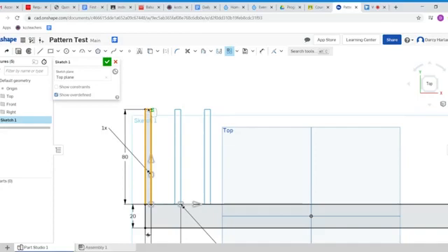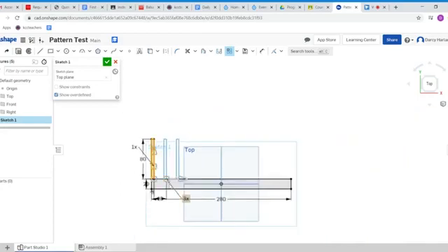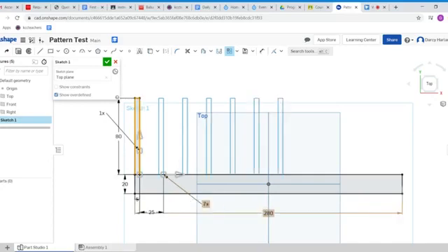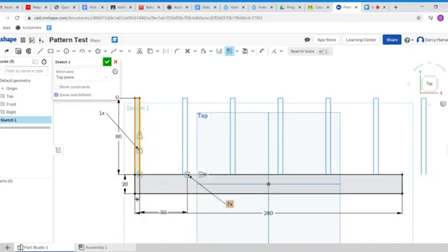So just select those 3 lines there, and you'll notice there's some other information that comes up when you have selected this. First of all, it's giving me 3. Down here, this little box is telling me how many times I want to repeat this pattern. So 3 times here. I'm going to go ahead and change that to maybe 7 times. Okay, and over here is the distance from this point to this point. Essentially, it's spacing out how big each pattern is. So we're going to change that. I'm going to change it to maybe 50 mil.